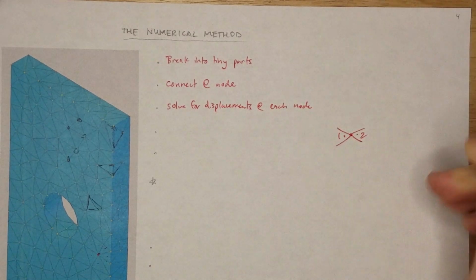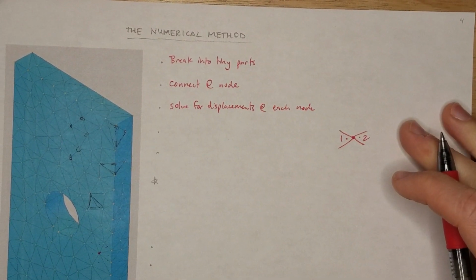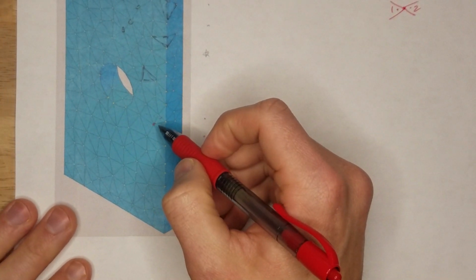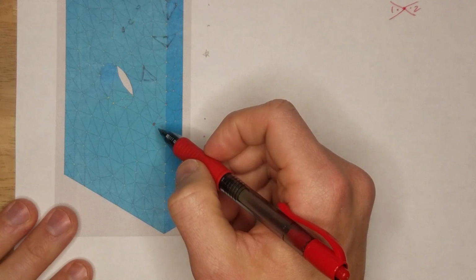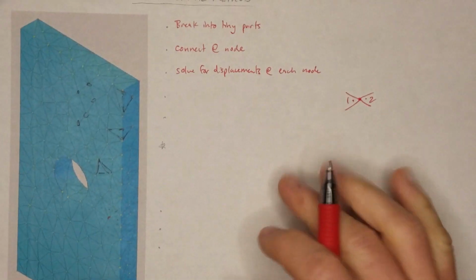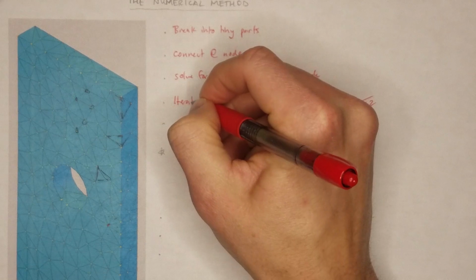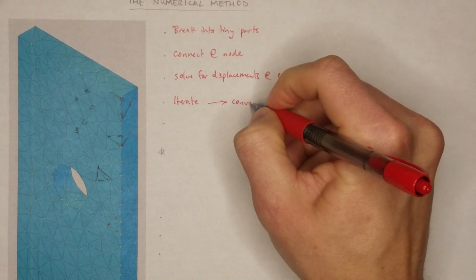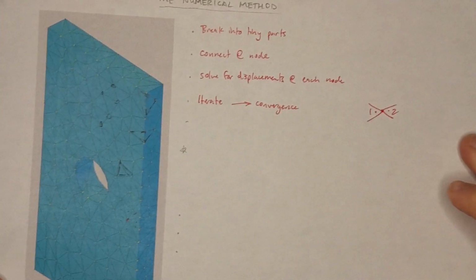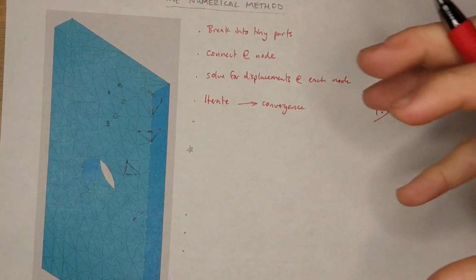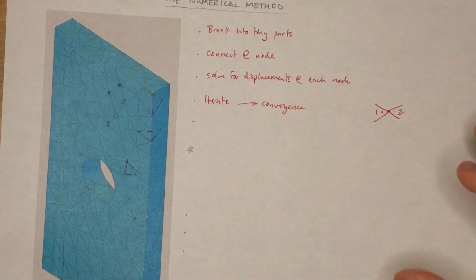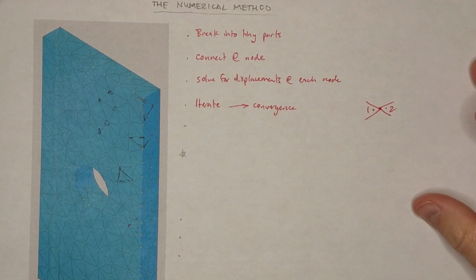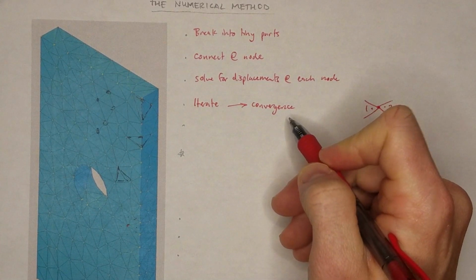Now, the software is going to do this iteratively. So the first time it solves each of those 7 equations, they're going to have 7 different values. And they may or may not be very far apart. And it's going to do this iteration over and over and over again until I reach some type of convergence factor, convergence criteria. Convergence means eventually those 7 formulas are going to be solved closer and closer and closer until they approach one value. And there's a percentage cutoff you can assign. And convergence is a measure of accuracy.